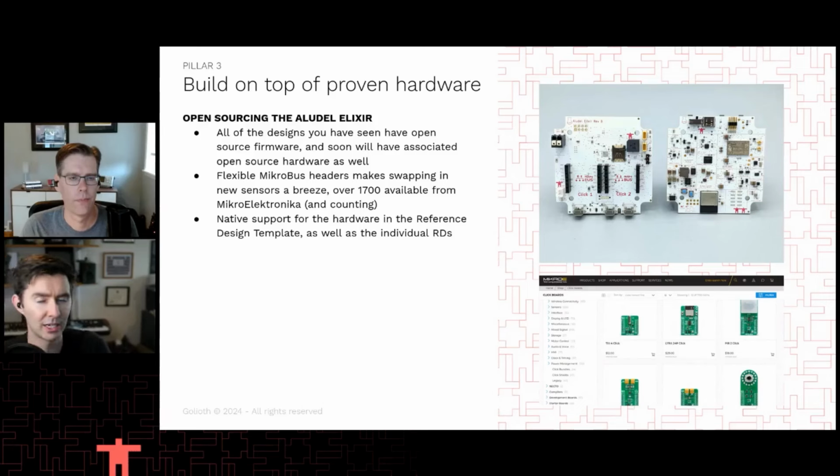And then when you do, you can take these files, which are open source, and use them as the basis for your design if you want to. It's a great roadmap to follow too. For instance, if you start with one version of your device and you have 5 revs of it, you want to be able to build for the latest rev, but also go back and build for other revisions. So we keep a separate repo for each of our custom devices. This Elixir that we're showing in the picture has its own Zephyr board definition, but that definition has different versions that you can build for without changing anything in your project. So if you're interested in that, it's a good place to look.